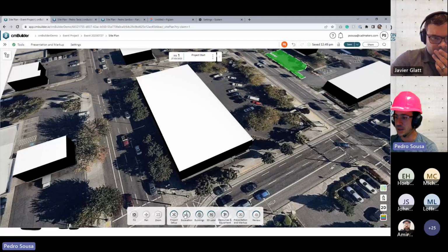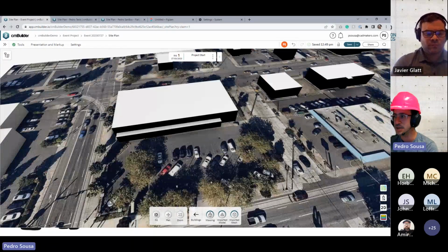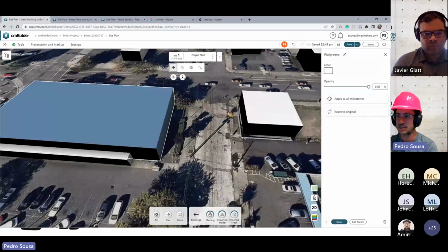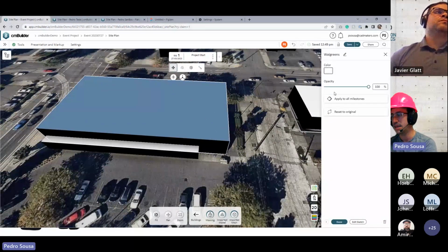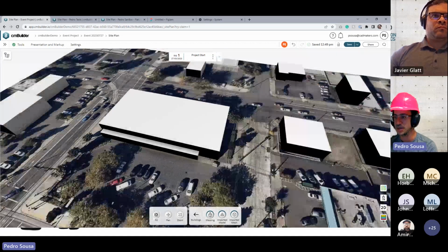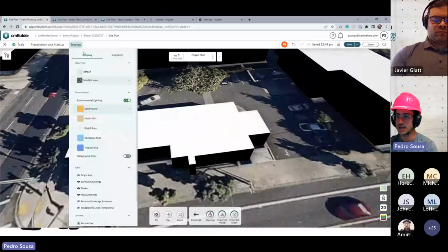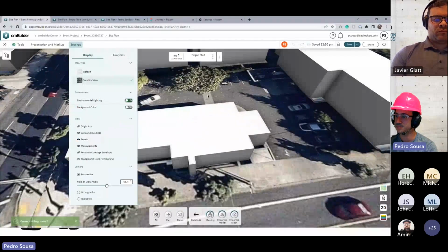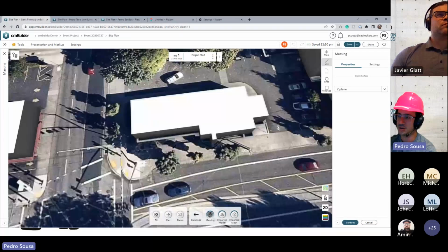Just to recap this part, you cannot create demolition stages with an existing building, because the existing buildings, the surrounding ones, don't have the timeline configuration, right? So you have to replace this with a simple massing. Let me see if I can find a more complex building, this one over here. So the easiest way to do that, and I'm going to turn this off, is to create a massing, go into simple massing, click to add a volume, and start your sketch on the ground.